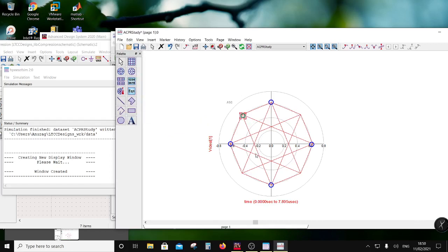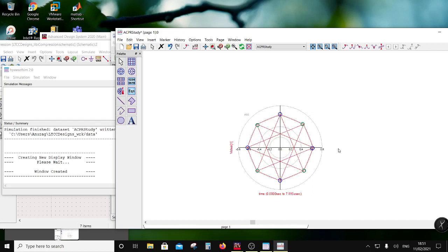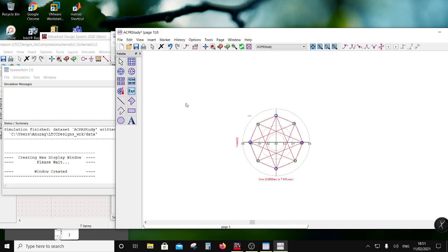Copy and paste. So you understood that there is a phase difference of 90 degrees in each group, but the two groups are 45 degrees apart. So this is your ideal DQPSK, and this is with a power of 0 dBm.